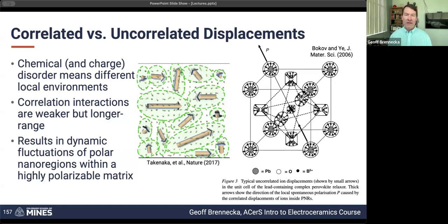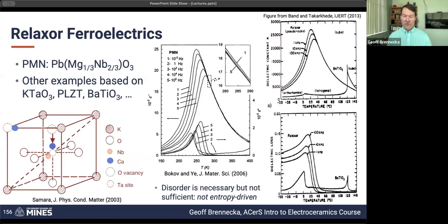So let's go back to this slide so I can talk to the diagram. So let's say we've got a miscellaneous perovskite here, and we want to add something. I'll use PZT, and we're going to throw in a lanthanide. So in PLZT, lanthanum is smaller than lead, but it's large enough that it really can't fit very well on the B site.